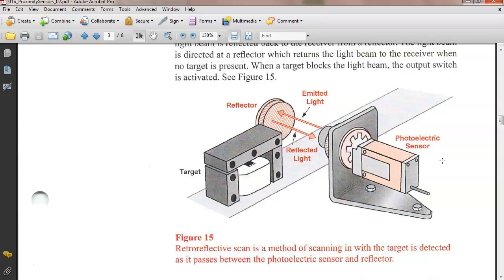You understand that? So through the beam, you really got to align the transmitter and receiver up. Here, you don't have to be near it. So these guys are true when the object is detected. And then when the object goes through and breaks the beam, then these guys become false.